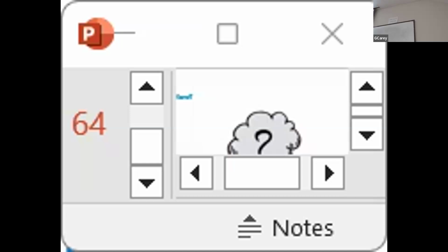So looking at some curves just real quickly, I think Willie will probably touch on it a little bit next week, but we have some system software selection program from Bell and Gossett. This was just a couple of quick examples that said, hey, if I had conditions of 100 gallons a minute at 100 feet of head, plugged it into that software to pick a pump, it picks a particular model number pump at a speed of 3450 RPM, 100 gallons a minute at 100 feet of head.